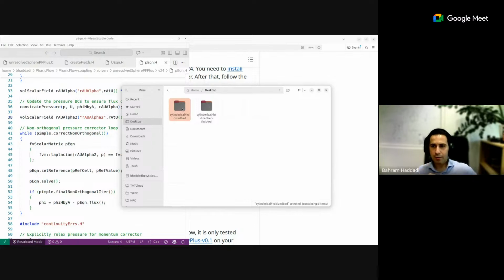Yeah, thank you. That's a very good question. Now I can maybe take a step back. If you run it in serial mode for the DEM, definitely it will take the longest. If you run it on the CPU, it takes probably longer than the GPU, but the GPU is usually the fastest one. The main limitation with the GPU execution is the number of particles. But since in this case, I'm looking at the 50,000 particles, that should be quite fine. With my GPU, I can run up to a few million particles.